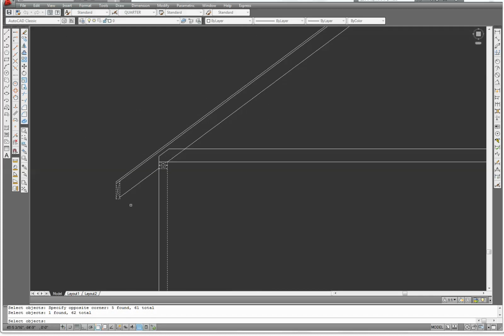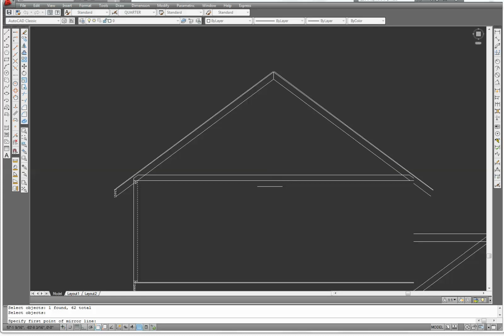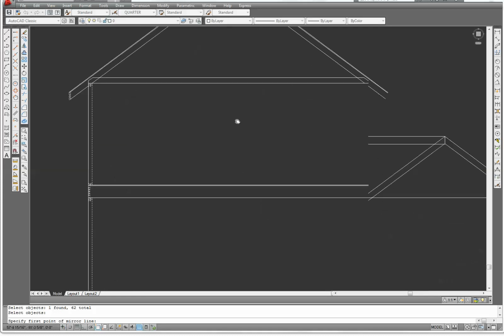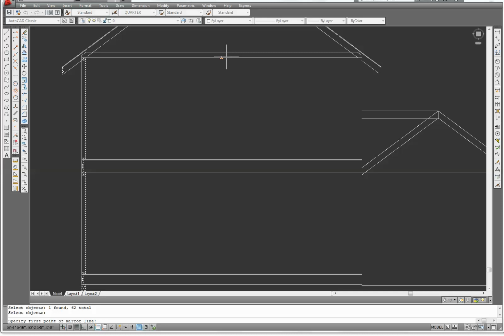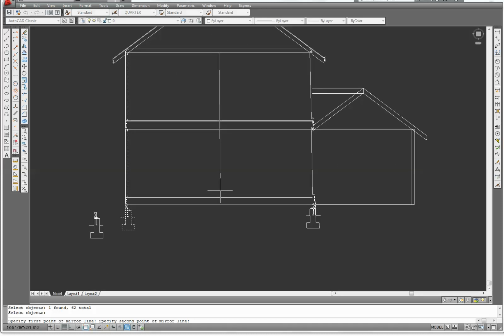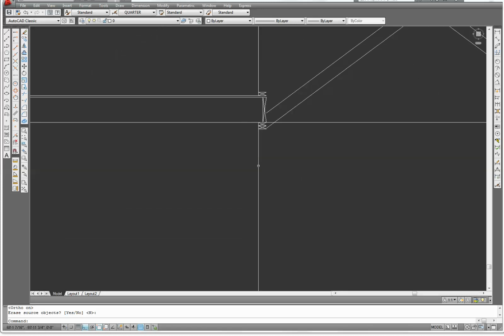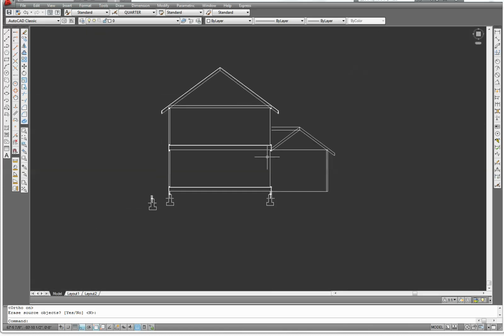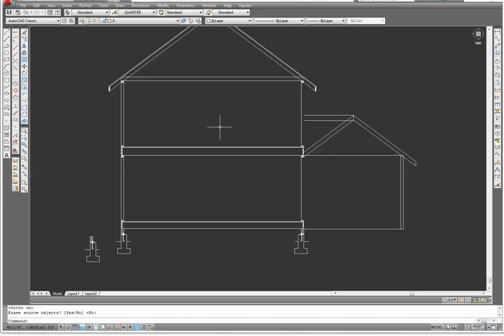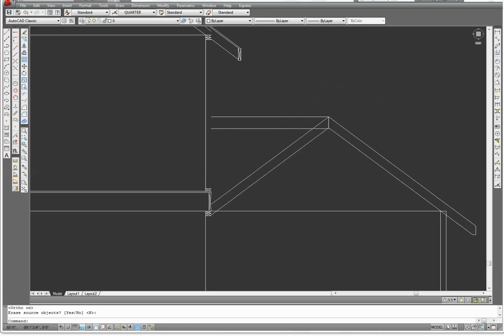Now, enter, and we need to have our object snap on, and we'll come up here and we'll click on the center point of this line here, the midpoint icon, and we'll come down. Let's go ahead and turn the ortho on, F8, and we'll just come down here into space and click. You'll see everything disappears, but when we enter, it comes back in again. And that did not work for some reason. Oh, it did work. We just didn't get this other outside line in here.